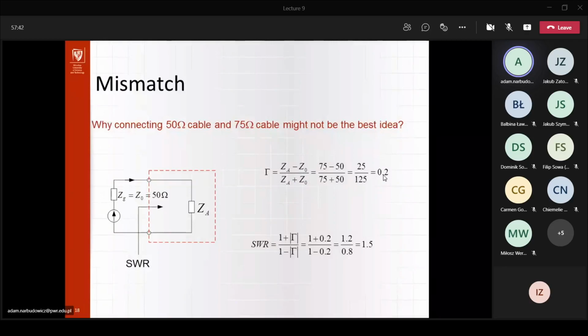And a signal reflecting from the antenna is, as I said, not a good thing. Firstly, because if it doesn't reach the antenna, it can't be transmitted, so you're less efficient. But the other problem is that the standing wave or the signal reflecting back may actually damage your active components in the transceiver, or drive them into the nonlinear range, which we'll be talking about next week.